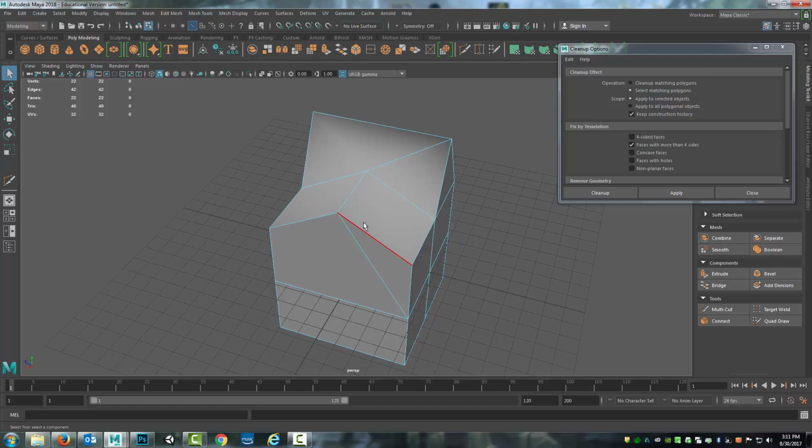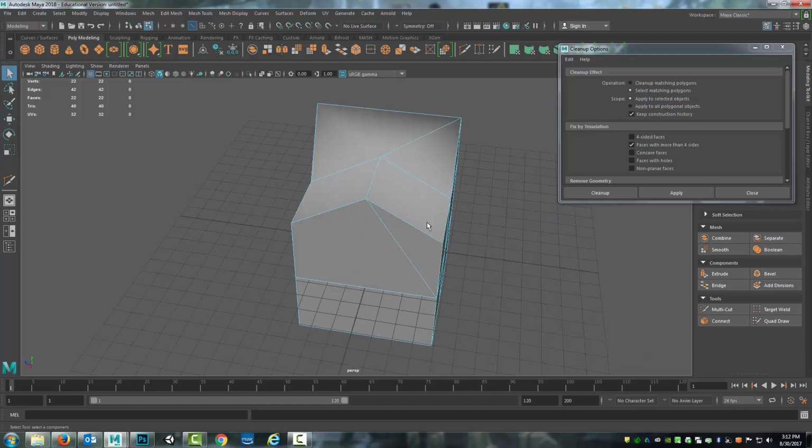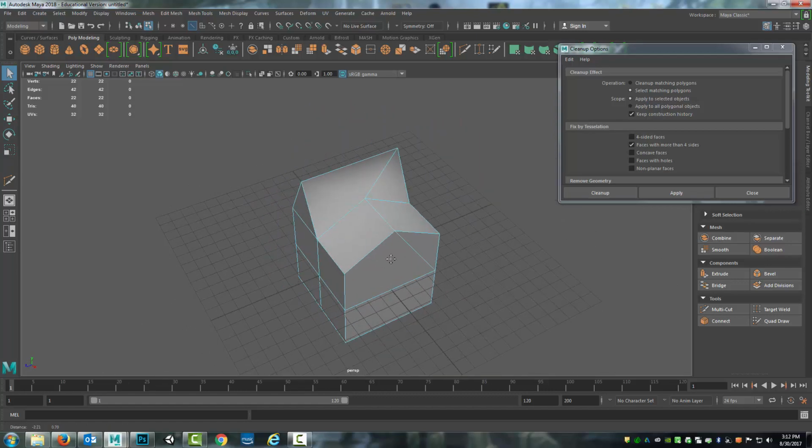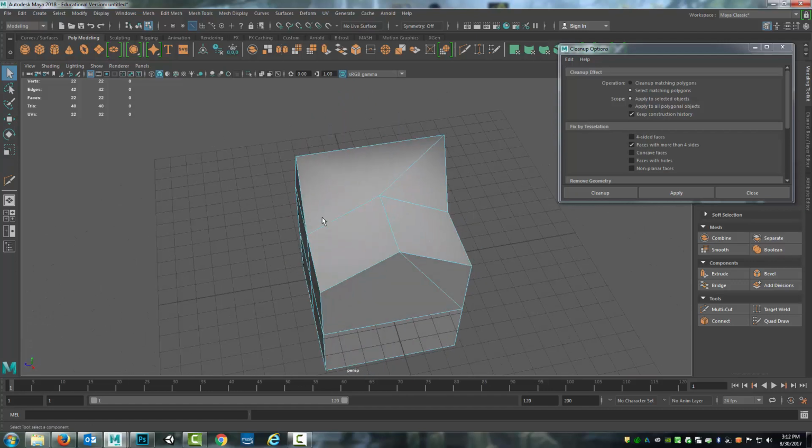It's also important for when you go to advanced techniques such as doing normal map creation and things like that. When you need to have subdivided surfaces, if you have triangles in there, it doesn't properly split it up and subdivide it. It gets these little memory sinks where you get the weird loops that go to a central point, and it takes up all of the space. So it's very important right now to not use triangles.